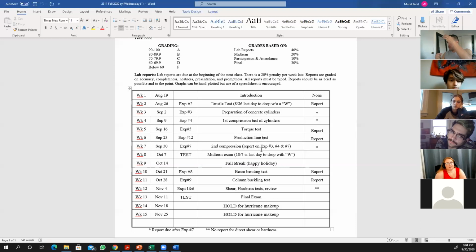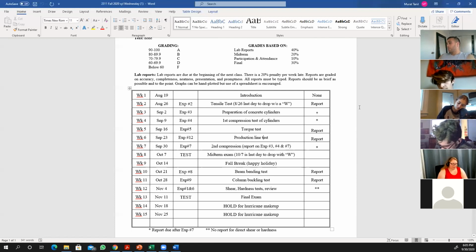Let's say it fails at 100 pounds, and then I take my sample, and my sample fails at 100 pounds. And then Tim gets his sample from the same spool with the same diameter. You assume that it's the same diameter because it's advertised on the spool. And I measure it, and I get 98 pounds. And then Andrea gets hers from the same spool, copper, same material, she gets 97. We look at the statistical analysis of the results, and then we calculate the standard deviation for the samples that we test.